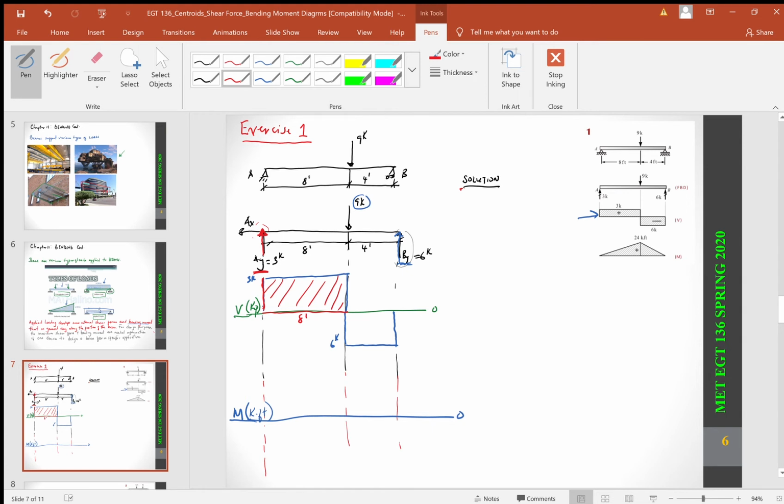So when you translate this geometric shape onto the moment diagram, it's going to be a straight line like this. So here's going to be 24. Now, as you notice, this particular geometric shape is below the 0 line, and it also has an area of 6 by 4. This is 4, which is 24. So that brings it back down to 0.